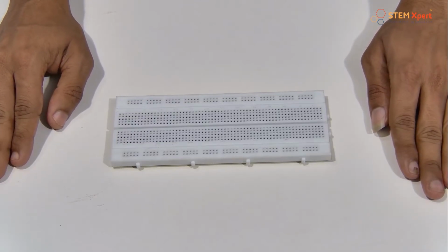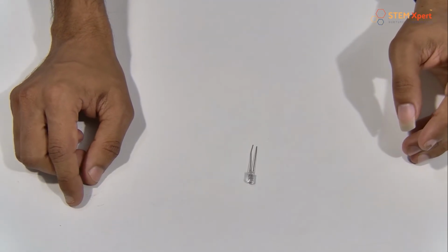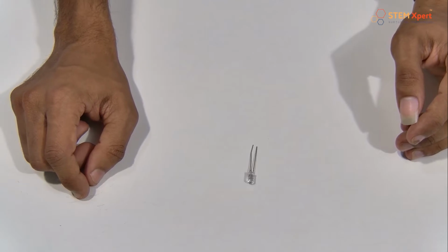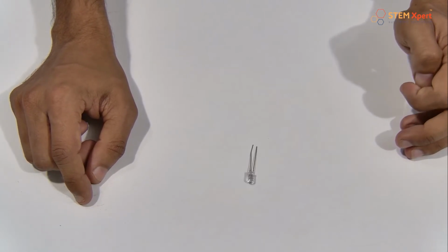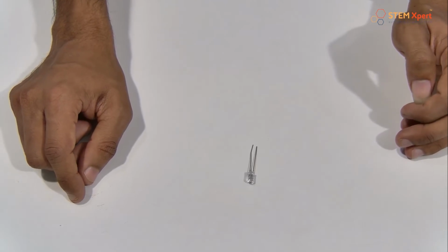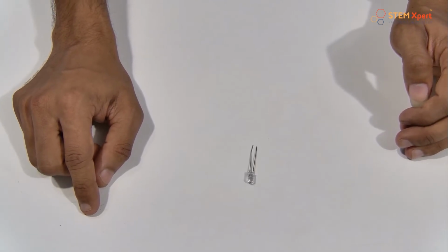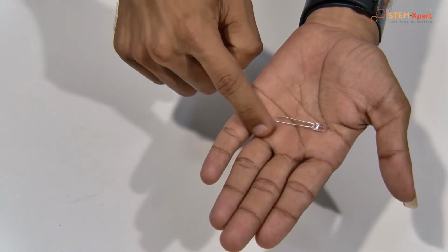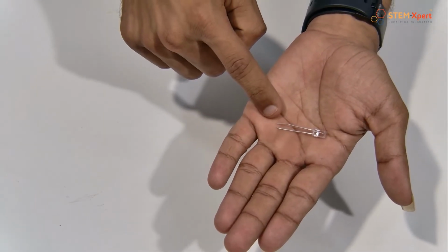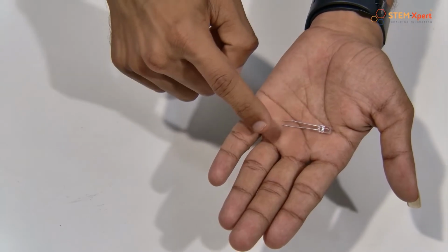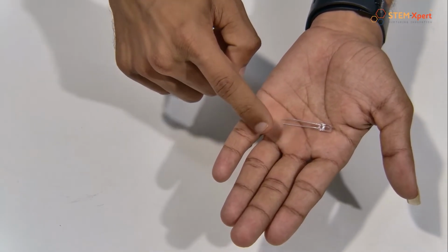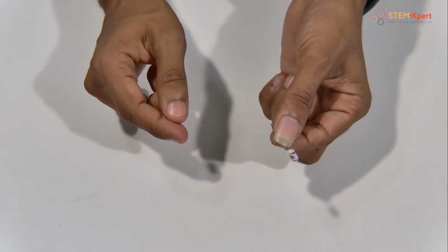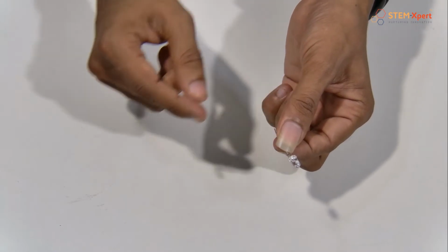Okay, so now let's discuss what an LED is. Do you know what an LED is? Yes, you have seen it in night lighting, art lighting, etc., right? So basically LED stands for light emitting diode. That means when we give electrical energy, it gives light as output. Also here in our LED lighting circuit, the LED acts as the load, right? Basically an LED has two terminals, one larger terminal and one smaller terminal. The larger one is the anode or positive terminal and the smaller one is the negative or cathode terminal. Also remember one thing: the LED works only if the positive is connected to the positive of the battery and the negative is connected to the negative of the battery.